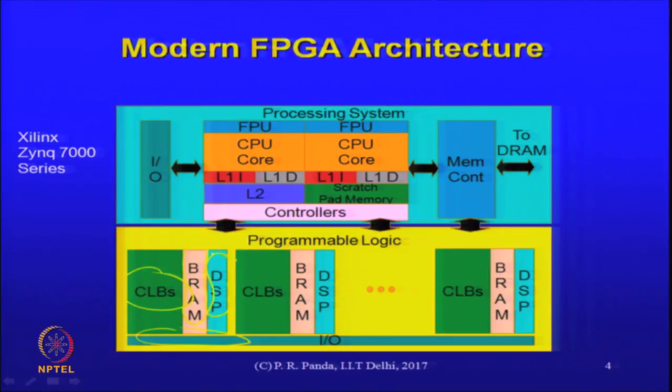Those are important. When we say combinational logic block, we are essentially talking about discrete logic. Of course, you want to augment that with some powerful arithmetic components also. So, that discrete logic block might already have within it some adder logic at least, because it is so common. But multipliers are more expensive and they may not necessarily be part of that standard combinational logic block, they may be externally present, distributed again throughout the fabric. So, such components are there.